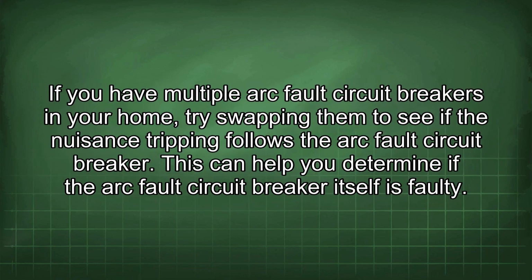If you have multiple arc fault circuit breakers in your home, try swapping them to see if the nuisance tripping follows the arc fault circuit breaker. This can help you determine if the arc fault circuit breaker itself is faulty.